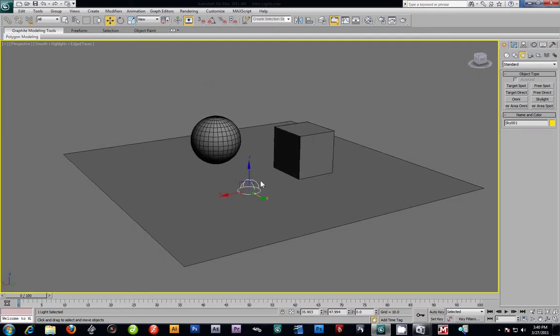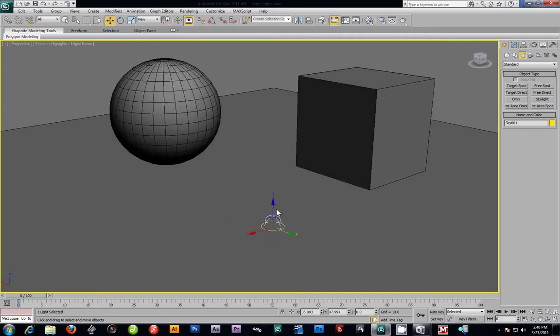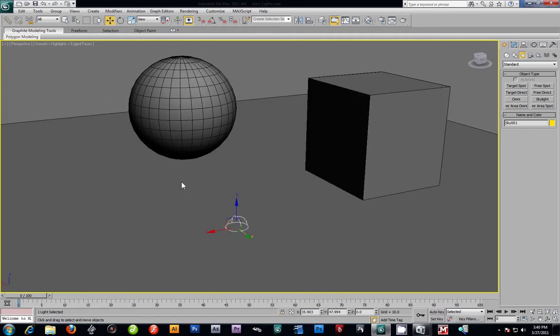And what this was, it creates a dome that has practically almost like 100 spotlights that circle the area, so it gives you all your soft shadows. Now what I basically do now is I teach you ambient occlusion pass in mental ray. So we don't use this as much, but sometimes it's good if you want to set up a render and have some simple global illumination.